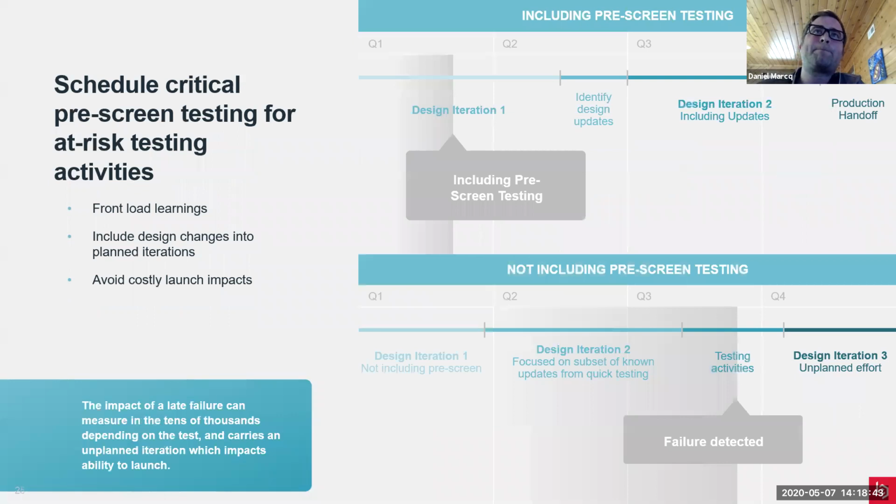So on this slide here, what I want to talk about is pre-screening testing. This is something we do very often at Bresslergroup, and it's had wide success for us on many programs. It's very important that you try to pull in your critical tests early and often. Again, reflecting on the last slide, think about environment. Think about FCC, think about UL. Anything you can pull in and get some of the prelim testing done will benefit you later.